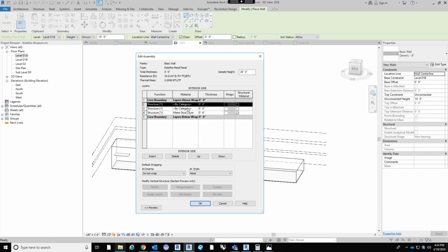So this builds a wall type, builds the layers of the wall. So in a typical wall, we'll have the stud layer, and then on the inside, which you can see is defined here and here. So the exterior is near the top, interior is near the bottom. On the inside is a finished wall, or typically what is considered drywall, gypsum wallboard.